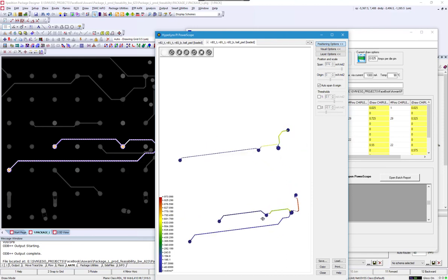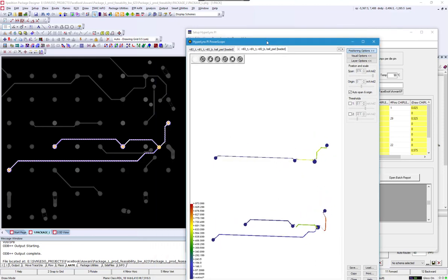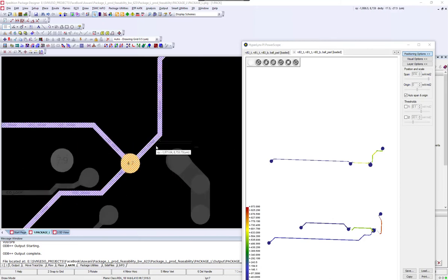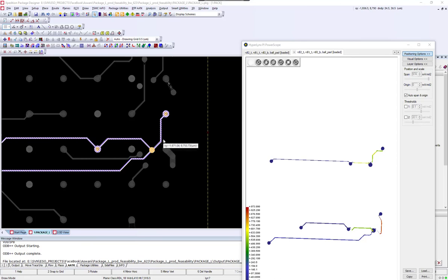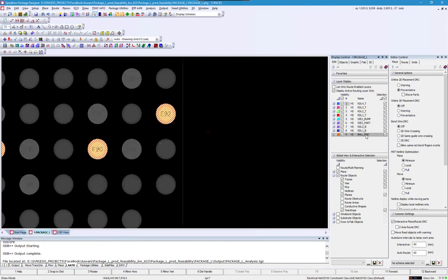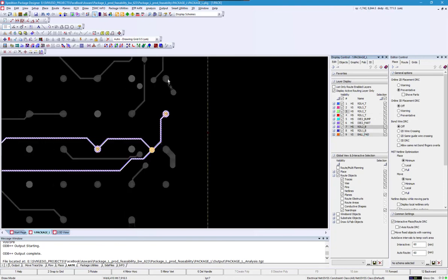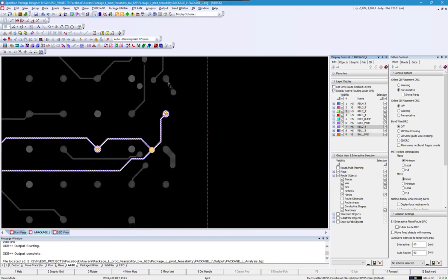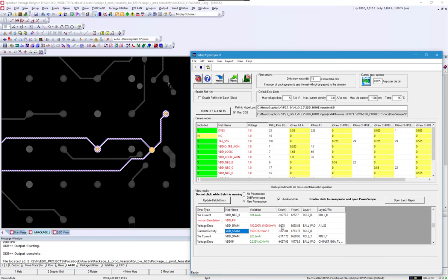So we're looking at this net, and if we look at it, let me move that out of the way. It's complaining. It puts a little X on there for us. The little X is right here, and it's saying this part of it has a current density issue. And the reason it's probably doing that is it's coming from the ball pad. It's coming up and getting fed. So current density being a power routing through this trace, it just didn't like that at all, the current density.